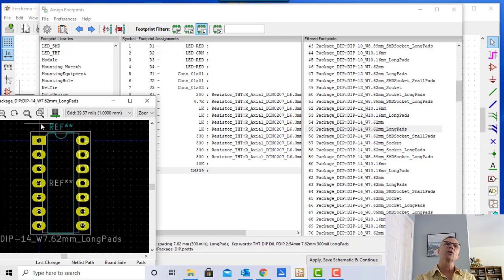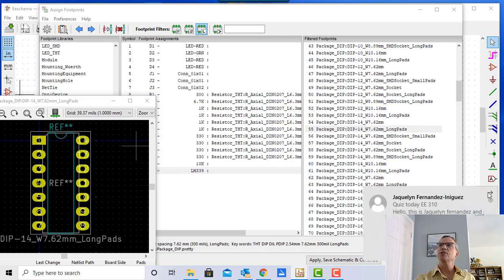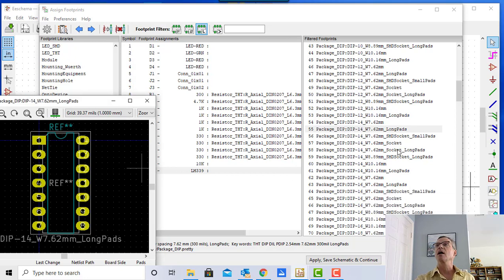So it's going to make it easier to solder. Now, take a look at the component outline. When we do our design rule check with our PC board, we better not put anything inside this outline, or the courtyard as they call it, otherwise we'll get a design rule error. Now for this part here, it is intended to not have a socket. So that means that the courtyard will be a little bit smaller than if it did have a socket.